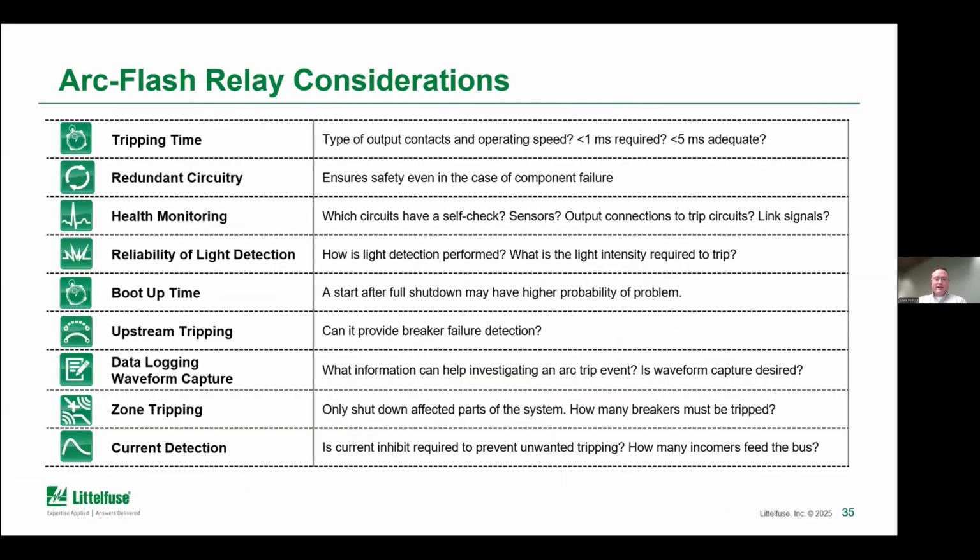So a few considerations when you're looking for arc flash relays on the system. One of the main things you want to look at is what is the tripping time. So when you look at reducing the energy on the system, what would you like that reaction speed to be? As I mentioned, there's devices out there that are 1 millisecond response, some that are 5, some that can be more. And that's one thing to keep in mind when you're looking at sourcing a relay.